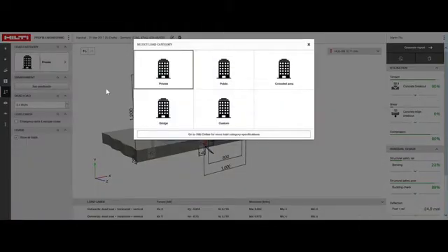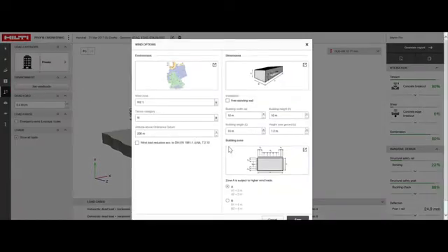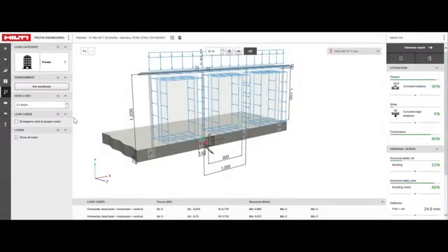Under the Loads tab, you can select what type of a building you're working on. The loads will be automatically selected based on regulatory conditions for your project location. Keep in mind that if the building is outside, the wind load needs to be set for each region. The dead load is the weight of the handrail, including the weight of cladding and flower boxes.